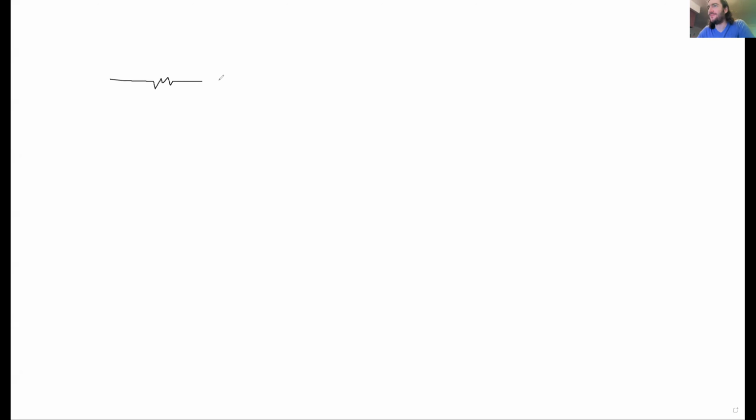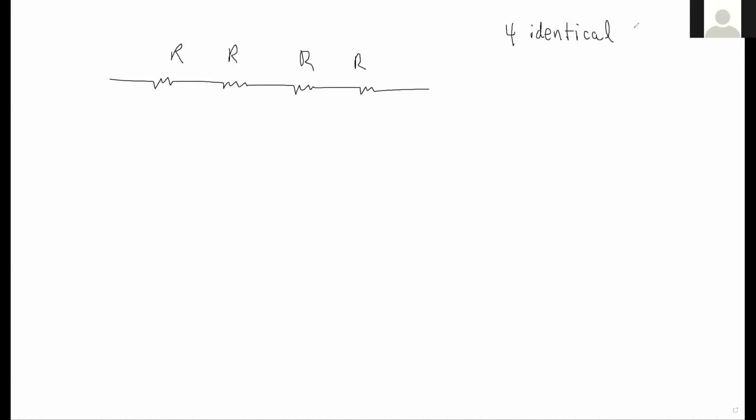Okay, can you see what I'm sharing? Yeah, I see what you're saying. Let me get you started here on it. So you're not missing out. So the idea is we have 4 identical resistors, and we connect them in 10 different combinations of series and parallel. So 10 combinations, and we calculate REQ for each of those configurations.